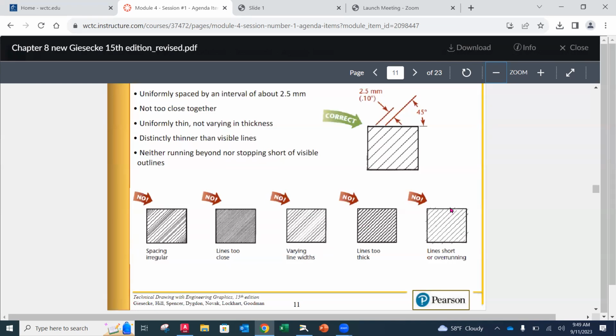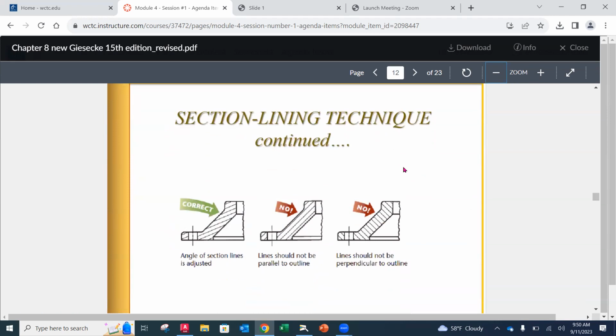And then notice that these are overrunning. They have to be within the confines of the area. This is where good geometry makes a difference, because if you have things closed up and they're single lines, AutoCAD's going to know exactly what you need. If not, that's where you'll have problems where the hatching isn't recognizing the area. That means your geometry was not created correctly, so that's where you have to go back to, okay? We'll talk about some of those situations when we start looking at AutoCAD.